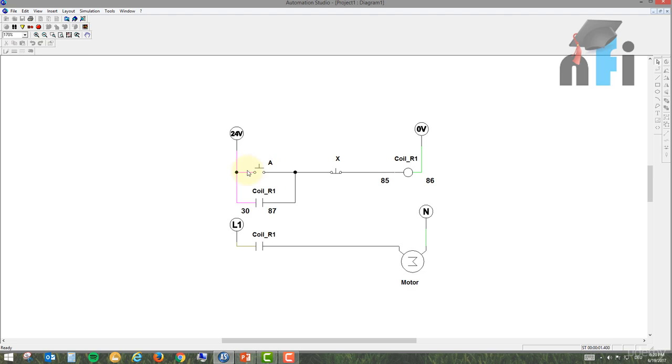So when you energize this one, you will see the color has changed. This will also latch my coil, and this will latch the motor which is running on line and neutral. This is a kind of isolation as well. If your motor is damaged, if it is a short circuit, this will damage this contact, but your relay will be safe. And this is how we also isolate high power circuits from low power control circuits. Like if you have a PLC, we connect a relay to the PLC outputs, and then we isolate the PLC outputs via relay to high power circuits like motors or solenoids.